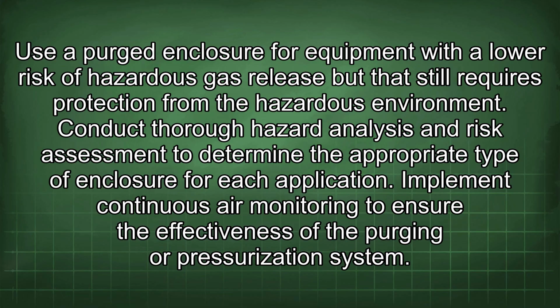Conduct thorough hazard analysis and risk assessment to determine the appropriate type of enclosure for each application. Implement continuous air monitoring to ensure the effectiveness of the purging or pressurization system.